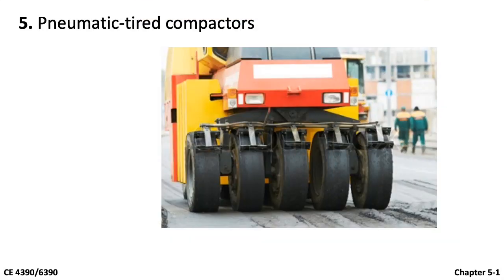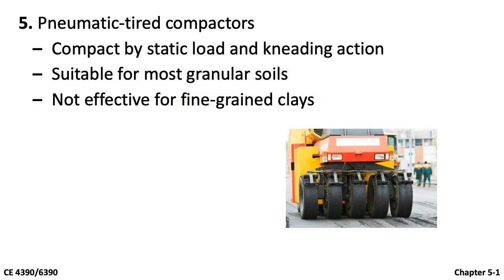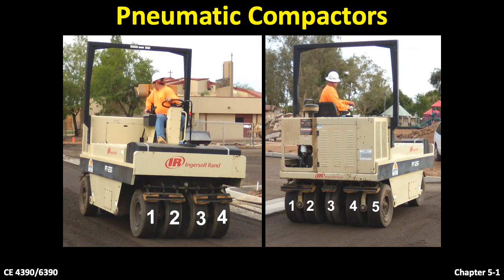This is a pneumatic tired compactor. It creates compaction by static load and kneading action. This machine is suitable for most granular soils and not effective for fine-grained clays. This figure shows the arrangement of tires. It has 4 front tires and 5 rear tires.